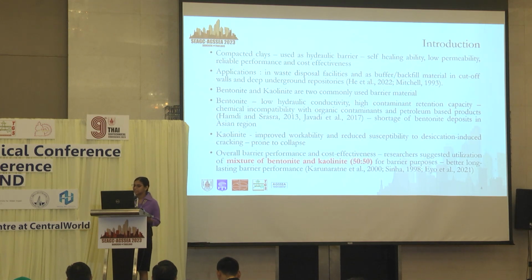Compacted clays are being used as hydraulic barriers because of their peculiar properties, such as self-healing ability, low permeability, reliable performance, and cost effectiveness. And they are applied in various applications, such as barriers in waste disposal facilities, and also as a buffer or backfill material in cut-off walls and deep underground repositories.